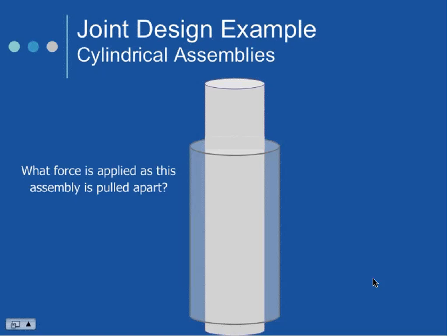Let's assume, and we haven't talked about this, but we'll just test your knowledge, that we're bonding polypropylene to stainless steel. It's a needle bonding application. I already know right up front that I'm going to have a challenge bonding to the polypropylene because it's a low surface energy material, right? What are some things you think we might try to maximize our adhesion if we don't get what we want?